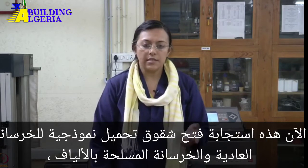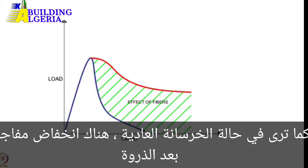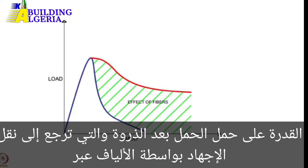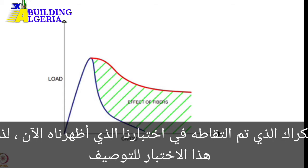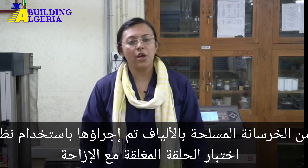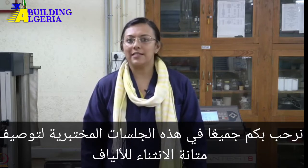Now this is a typical load crack opening response of plain concrete and fiber reinforced concrete. As you can see, in the case of plain concrete, there is a sudden drop after the peak, which shows a brittle failure. Whereas in the case of fiber reinforced concrete, there is an enhanced post peak load carrying capacity, which is due to the stress transfer by the fibers across the crack, which was captured in the test that we showed now. So this characterization of fiber reinforced concrete was done using the closed loop testing system with displacement control, and thank you for watching.